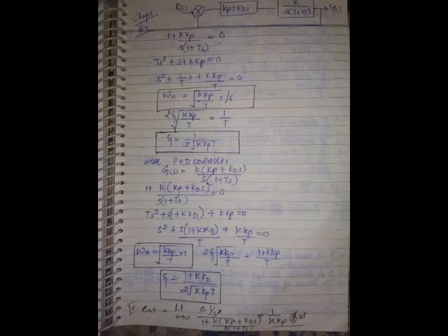But here, the anticipatory nature of the derivative controller you can control by changing the value of Td. If the response is very fast, then you can control that response by changing the value of Td. The advantage is that tuning of the controller is possible only in combined actions. So by appropriately tuning the values of Kp, Ti and Td, you can get optimum responses from these controllers. That is possible here, but for individual I and D it is not possible.